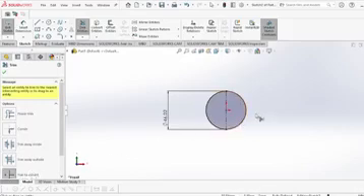Come here, you can see this line here is highlighted to this point because there's a line dividing the circle, so it won't cross over to the other side. So I don't need this part. What am I going to do? Bring your cursor to this. When it is highlighted, click to remove. Now I have just a semicircle right here. So it's used in removing.